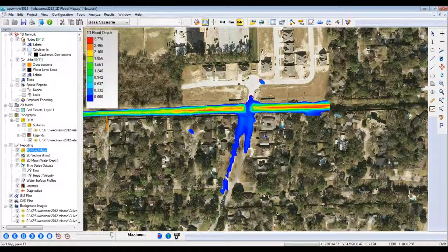It is worth being aware that although this is a useful tool for 1D models where you're not running an integrated 1D 2D model, it does have some limitations compared with the 1D 2D integrated approach, and you should just use a bit of caution, particularly where there's significant meanders in the model, and just consider whether a 1D 2D approach is going to be a better option.